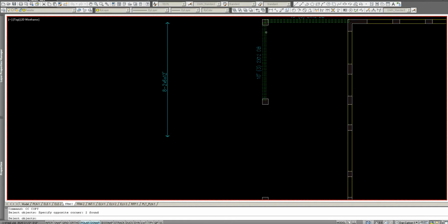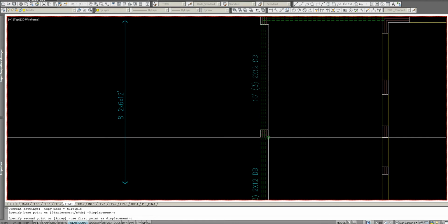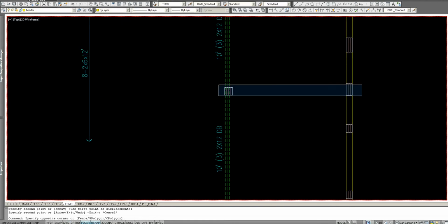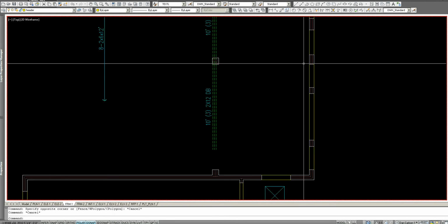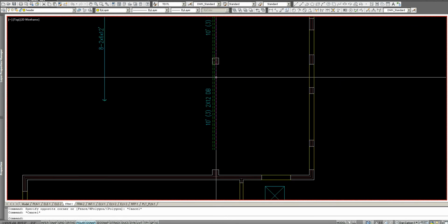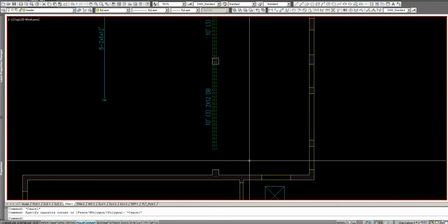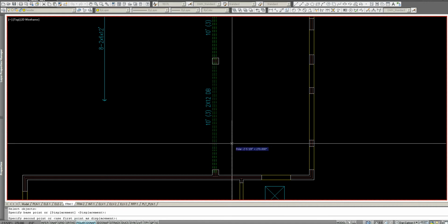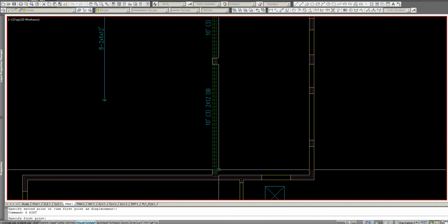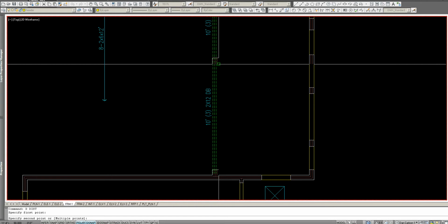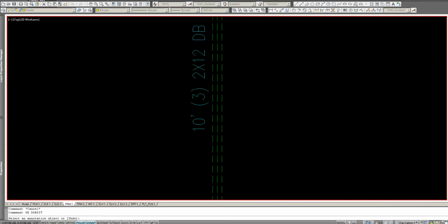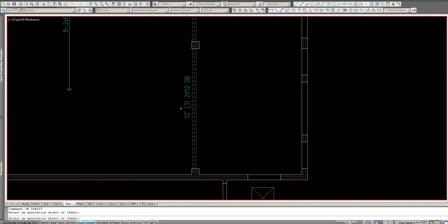And then this one is actually a slightly different span. The reason is I was trying to line up this column with this piece of wall here so that the windows to the family room had a clear view. So this span is actually wider instead of being equidistant. This is a 11-foot 4, which means we could do a 12-foot easily.